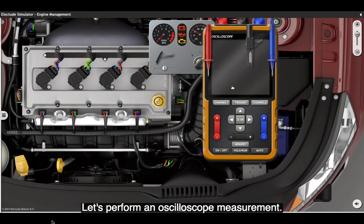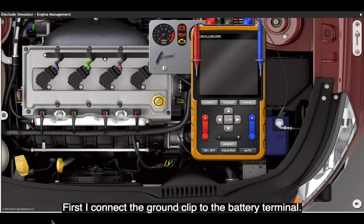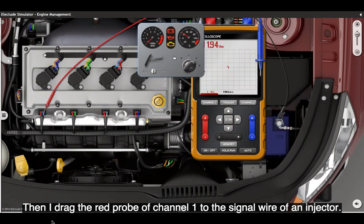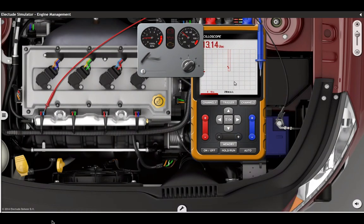Let's perform an oscilloscope measurement. First, I connect the ground clip to the battery terminal. Then I drag the red probe of channel 1 to the signal wire of an injector. I can zoom in vertically and horizontally on the signal.